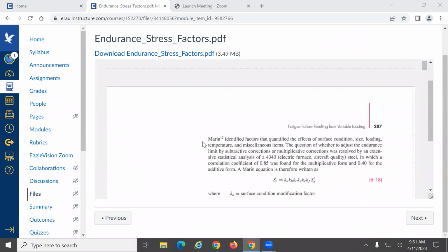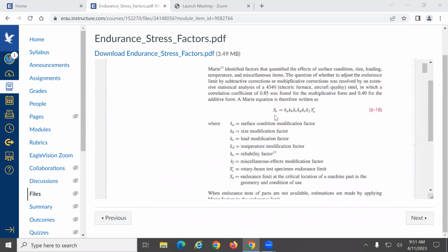So there's multiple factors, and then at the end it becomes ridiculous. Imagine what they tell you at the end: that the stress depends on 1, 2, 3, 4, 5, 6 factors, that concentration factor times that value. So personally, I just give you one for the stress concentration factors. And if I need to do the design, what I do is include all these ones into my safety factor instead of each one of them. I don't know if that makes sense for you, but they want us to look at that. So imagine how many coefficients you have.